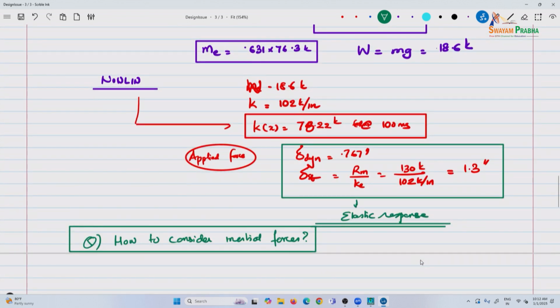The approach I took when you do a single degree of freedom system is Kx is what is transmitted to the supports, M is within the system itself, right. So, it is Kx, your spring force, plus your inertial force is equal to the applied force.